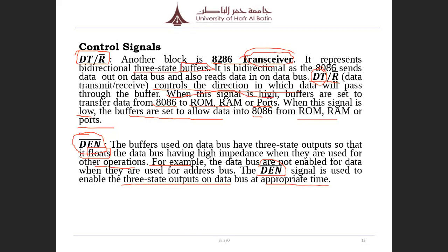When there is a data signal on the multiplexed address/data bus, DEN becomes low. The microprocessor makes a low signal to the data transmit/receive IC, so that data information can pass through this buffer.